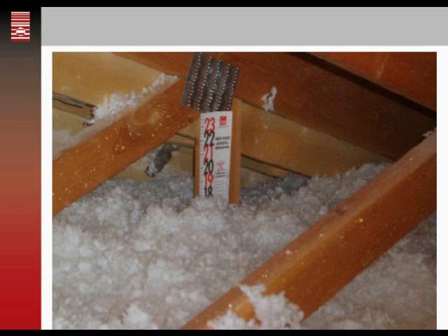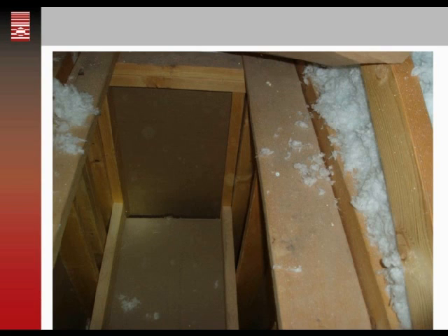She added 18 inches more insulation on top of the existing insulation. Now she's got 3 feet of insulation up there, and it made very little difference in the problem because the problem was not enough attic insulation. The problem was part of the problem was the huge amount of bypasses.